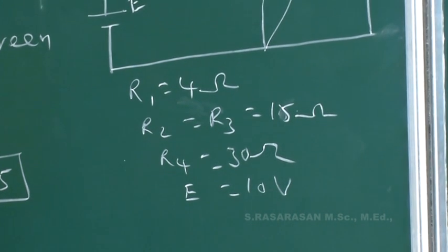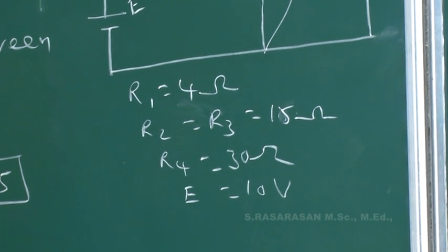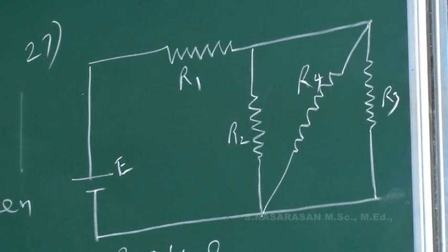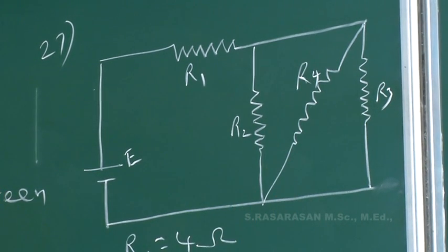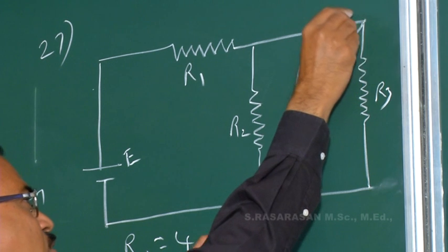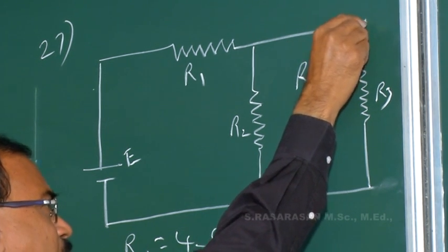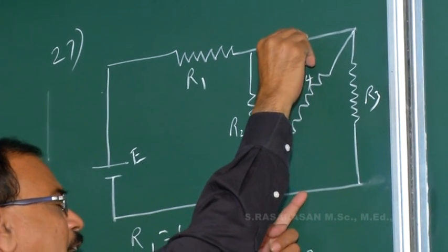The given circuit is a little bit complicated. No, it is a very simple circuit. Reason, in this circuit, this resistor is connected diagonally. The resistance is connected diagonally, that means instead of connecting the resistor in between these 2 points, this end may be connected here also, that is equivalent to connecting here.